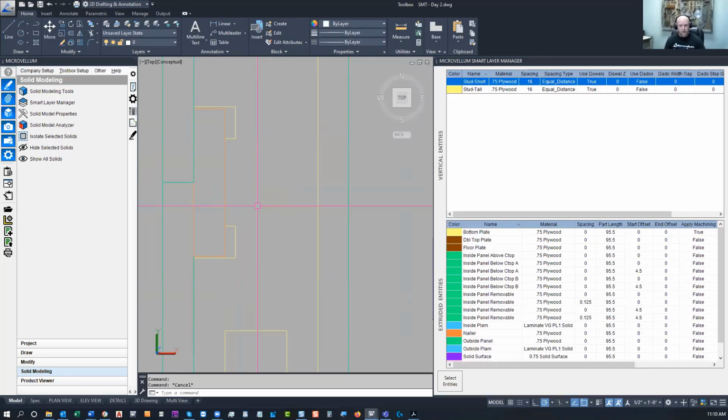Again, I'm looking for anything I can do to speed up the assembly side by engineering. By adding these corner relief notches, I don't have to worry about rounded corners coming in from my router, or maybe having to throw a round over bit onto my nailer so I can just slap that in. I can just work quickly and easily off of square parts and get to assembling this thing in no time.